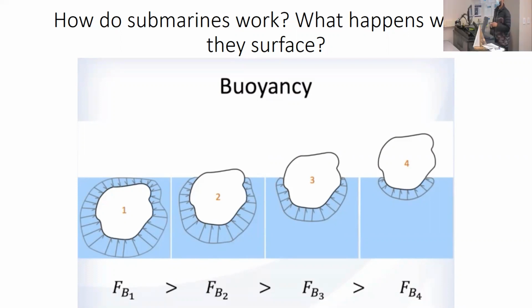Okay, neutralize your buoyancy. You said start decreasing your weight. Okay, how do you start decreasing weight? Do you start throwing stuff off the sub? Yeah, you pump some of the water out of the ballast tank. So you restore some of the dry volume. And you need to do it just enough so the buoyant force is exactly balanced by the weight. If that's not the case, you'll either start rising up or keep sinking.